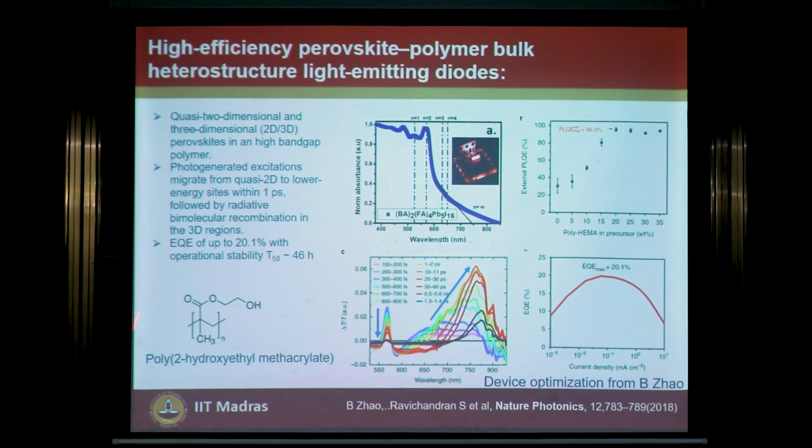So we use these very readily available polymers, and we put our precursor solution inside this, and we started spin coating the system. The first and foremost observation is the PLQE, photoluminescence quantum efficiency, which drastically increases as you start passivating the edge states of the quantum wells. You're talking about the edge states? And we believe it's only on the edge. The top is pretty insulating.